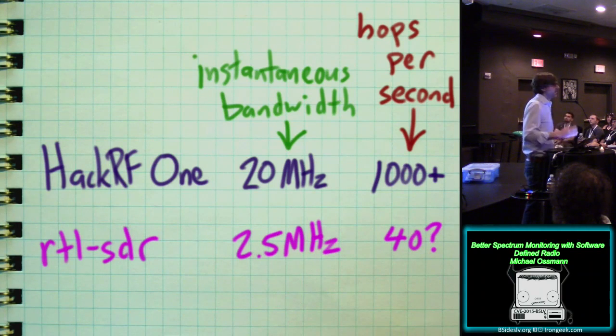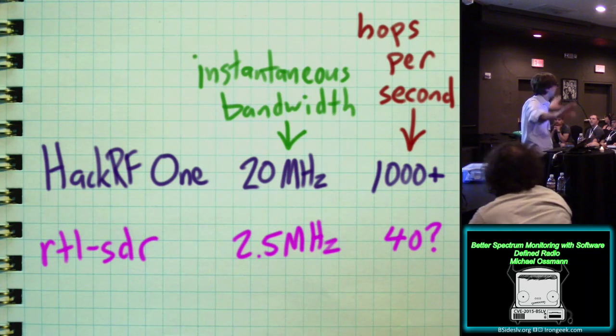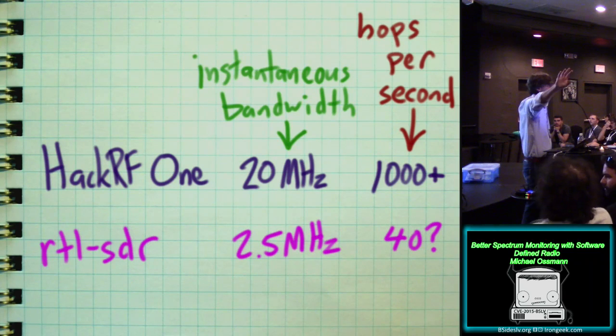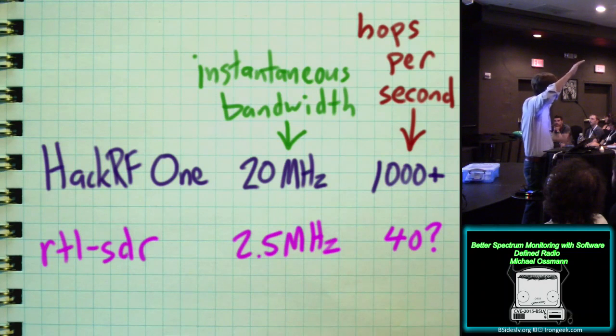So at 750 microseconds of tuning time, I can very easily achieve upwards of 1,000 hops per second. And that means we have much greater capability to make this observation. If you think of this two-dimensional, imaginary perfect waterfall plot in the sky that has frequency on one axis and time on another axis, and you think, how much of that big plot are we really measuring? Well, by tuning much, much faster, we should be able to fill that in and measure a lot more.